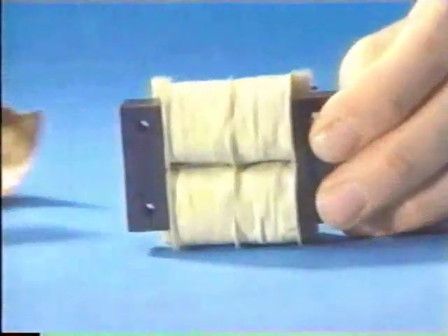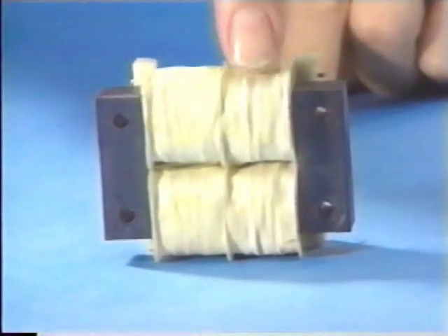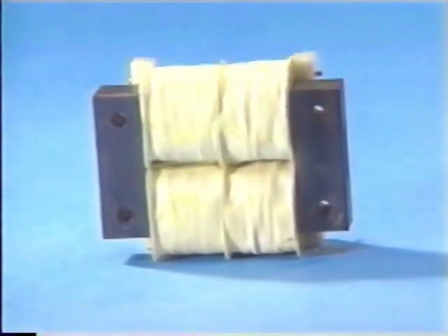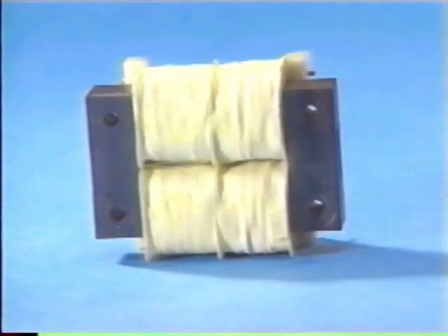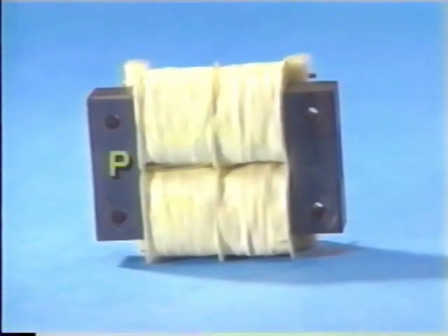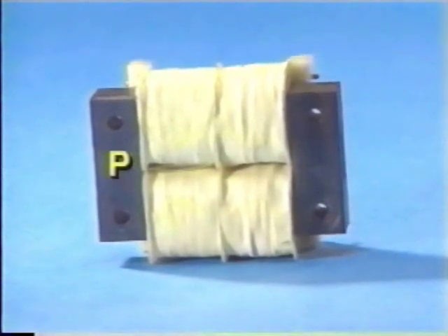As the cover is removed from this transformer, you can see the individual coils. Although they are wound very close together, they are neither physically nor electrically connected. They are electromagnetically coupled. The coil to which the AC voltage source is applied is called the primary, identified with the capital letter P. It generates a varying magnetic field, which cuts through the turns of the other coil called the secondary, abbreviated as capital S, and induces a voltage in it.